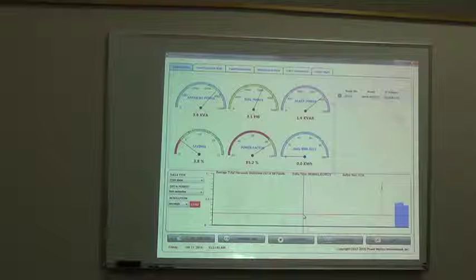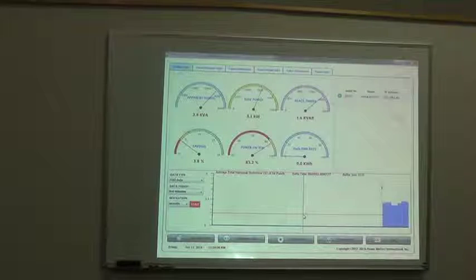Mitigation is this. I measure the harmonic before I turn the bank on or off, and I measure it after. If by my actuation of the capacitance the harmonics went up by a little bit, it's fine. But if it goes down, great.